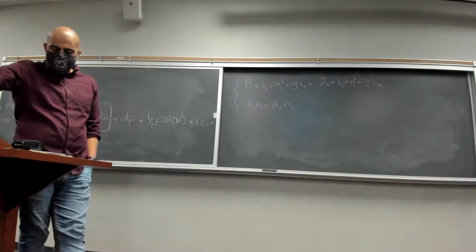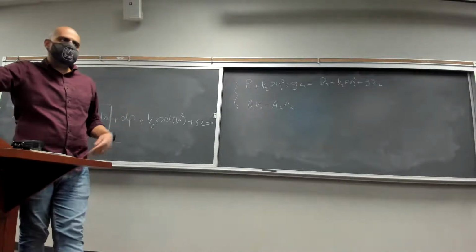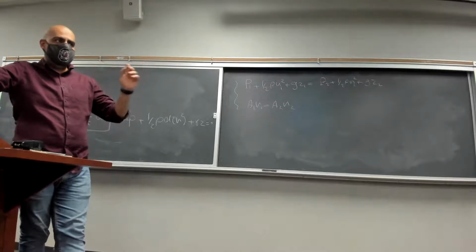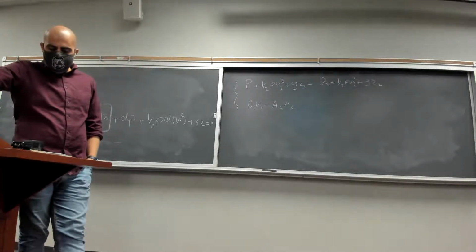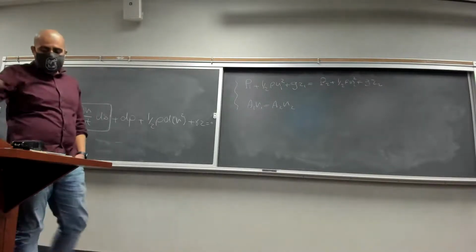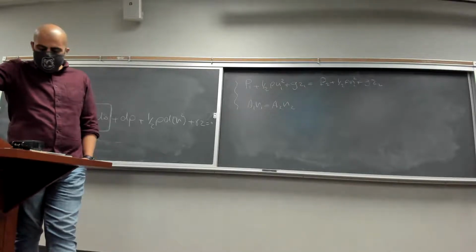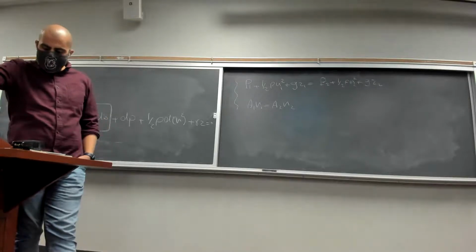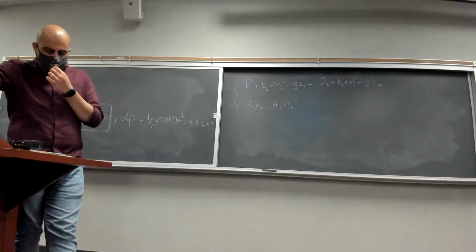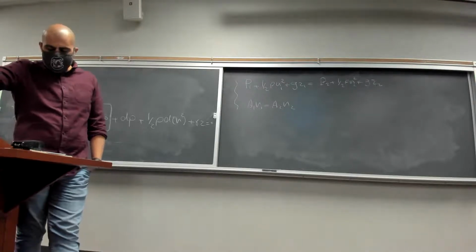So the problem is telling us air flows steadily, which means that it is steady state, right? Along a streamline. The second assumption was that flow has to be along a streamline. So 2 assumptions are already met. From point 1 to point 2 with negligible viscous effects. That's the third assumption, right? The flow is inviscid. We are neglecting the viscosity. And the following conditions are measured. At point 1, we have Z is 2 meters, P is 0 kilopascals. At point 2, we have Z is 10 meters, P2 is 20 newtons per meter squared, and V2 is 0. We want to determine the velocity at point 1.